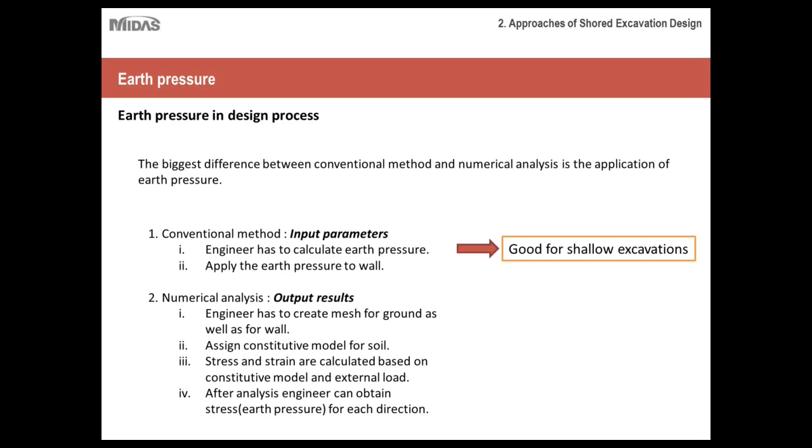So you must be wondering why we have to do numerical analysis when we can easily compute the earth pressure from the previously discussed formula. It's because when the height or the depth of excavation increases, these formulas and the variations that they propose are no longer valid, and therefore if you are dealing with deep excavations, you must use numerical analysis.